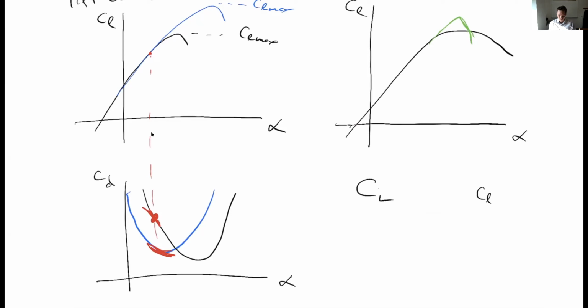Well, you probably won't be designing your airfoil in detail. A good thing you can do is to use some existing airfoils. Now, there are a lot of existing airfoils. You want to pick one that is designed for the kind of flow conditions that you're looking for, right? So we're going to be in low Mach. All the airfoils are going to be appropriate for that. But we're also going to be in a low Reynolds number, and not all airfoils are going to be good for that.